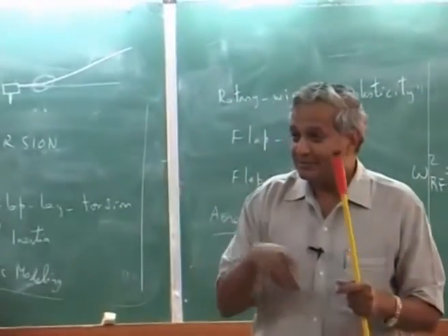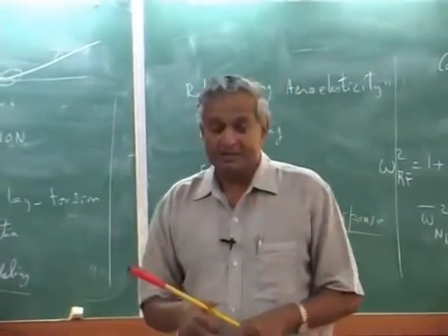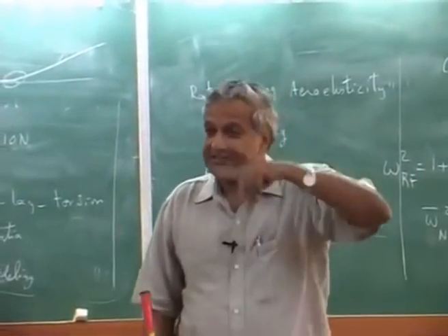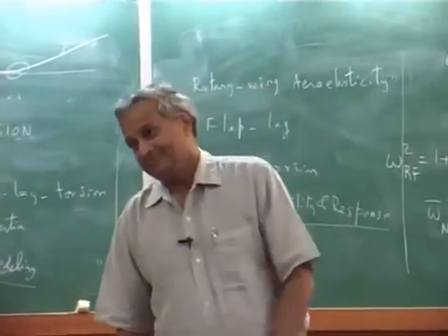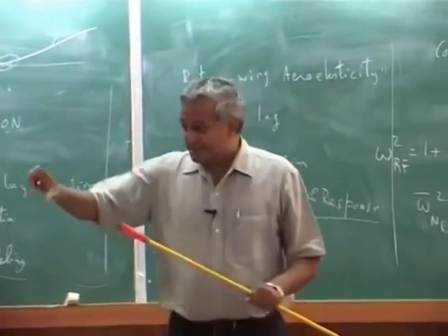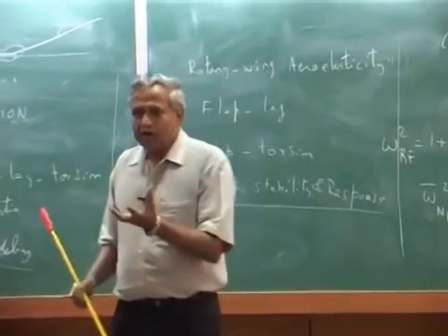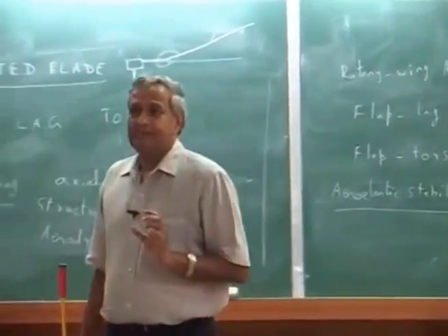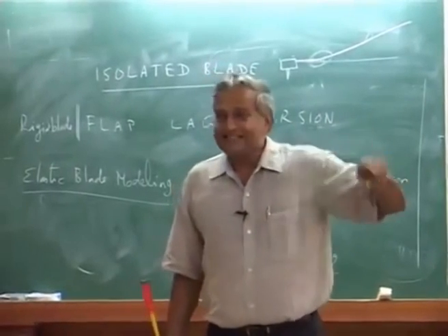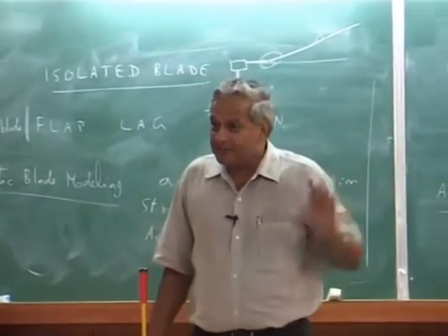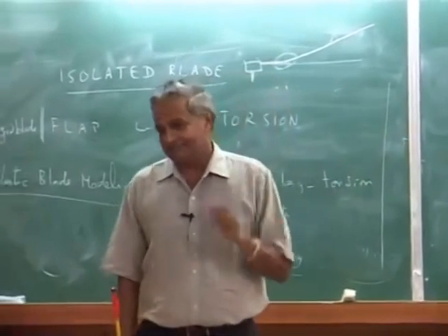But that does not mean flap load is useless, because that will give you the fatigue, because it will oscillate. All the vibratory load comes here, that is where the flap is, because it is a bending problem. Load wise, magnitude may not be very large, but this cyclic load, vibratory part is the one which is critical.